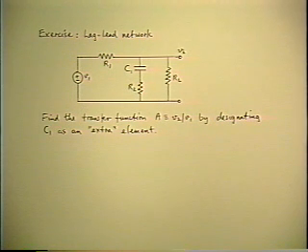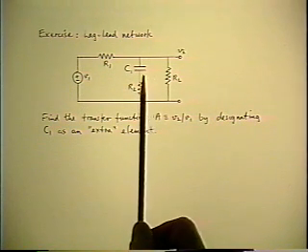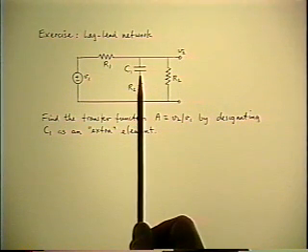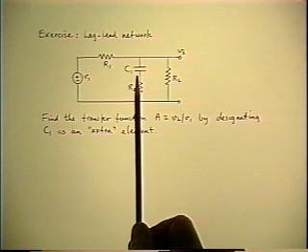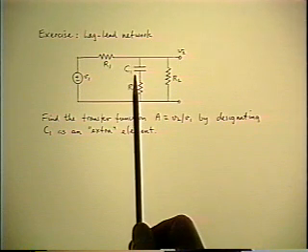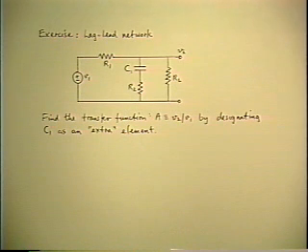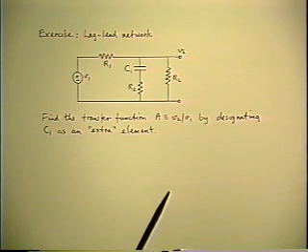And you notice that first thing is, even after you've chosen the capacitor as the designated extra element, and you throw it away, you're faced with a choice again. What do you replace it with, an open or a short? Yeah? Why?